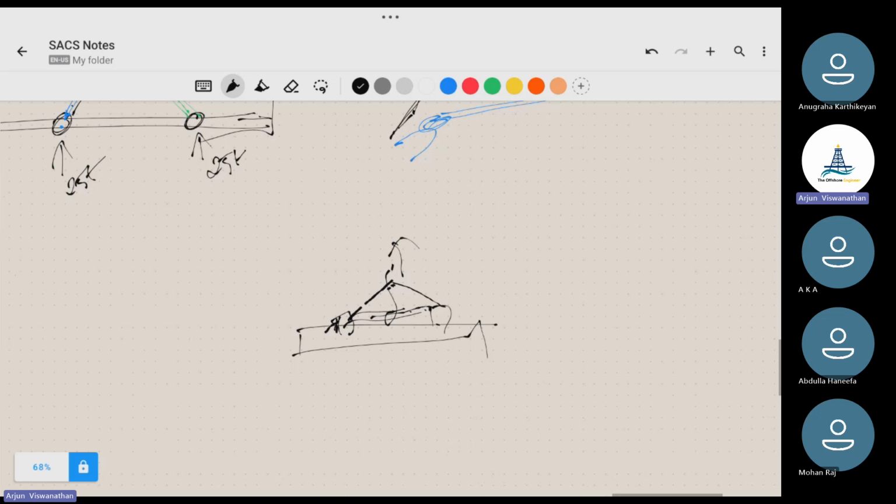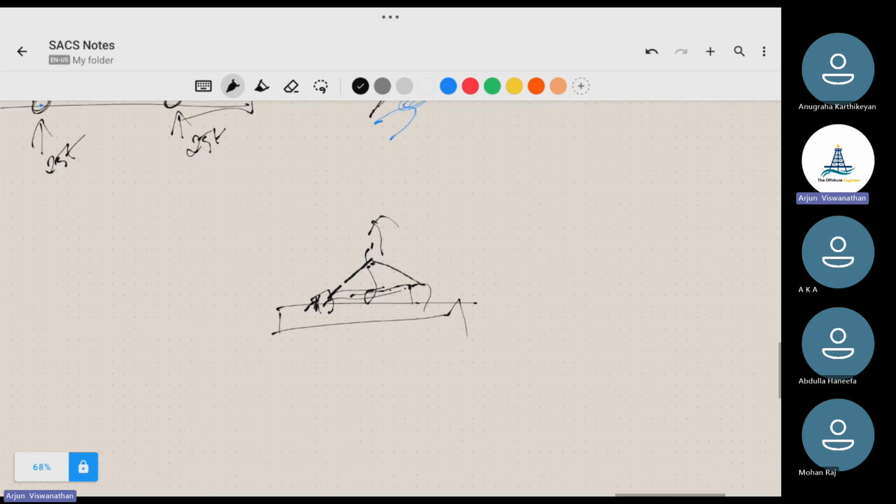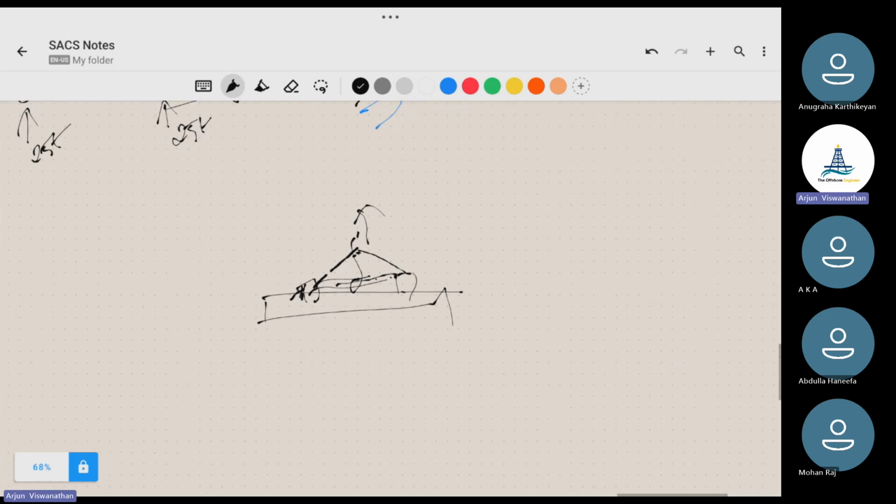That is due to fabrication mistakes, not anything else, because if we select a wrong length, that is a different mistake altogether. Here we are considering the ideal case. If we bought two slings, but due to a fabrication mistake one sling was extra in length, that is why this initial load mismatch happened.